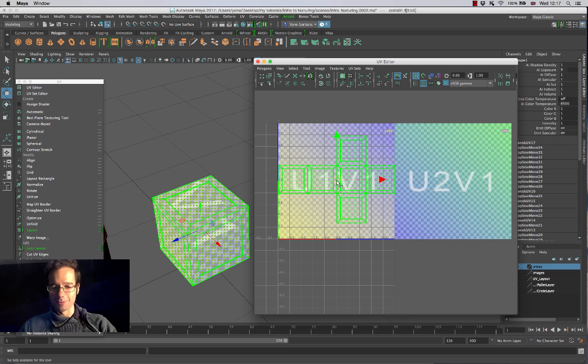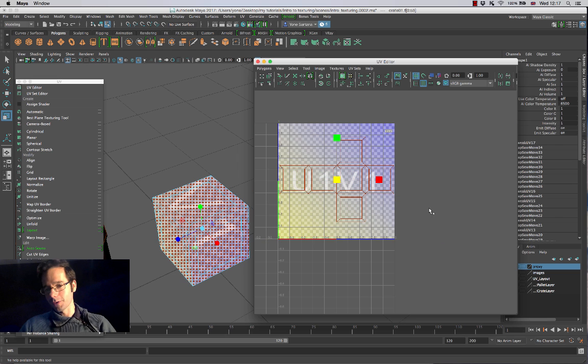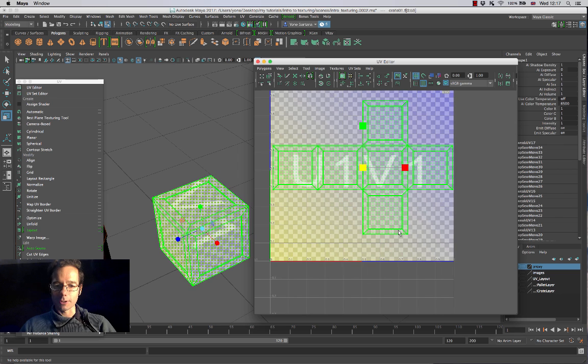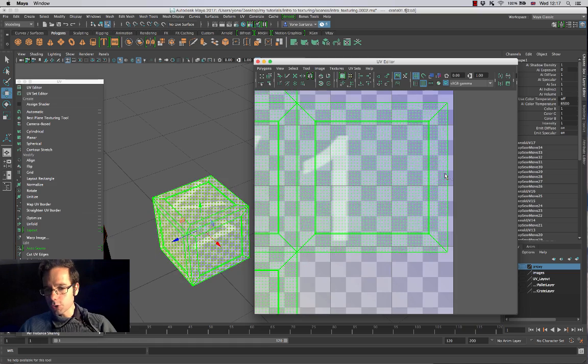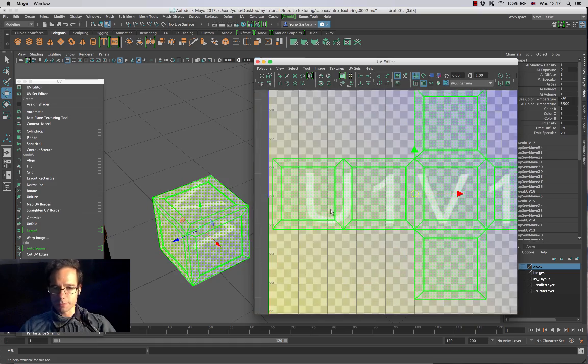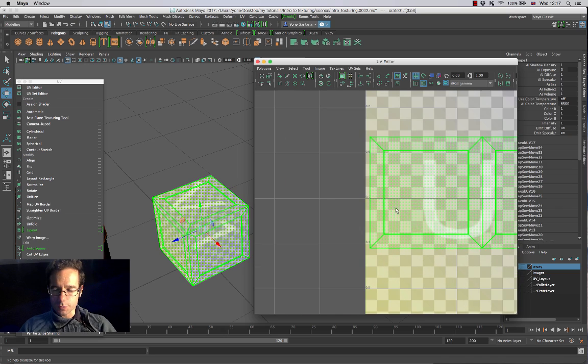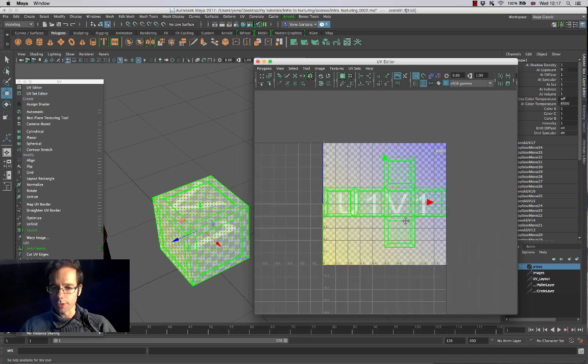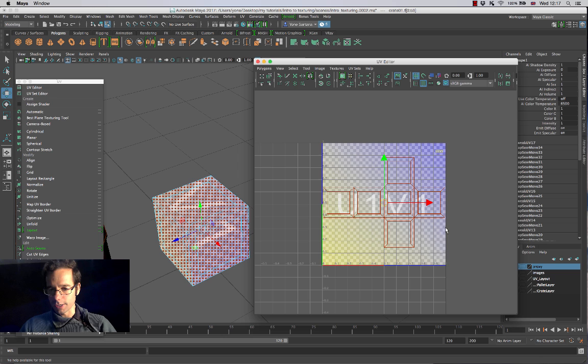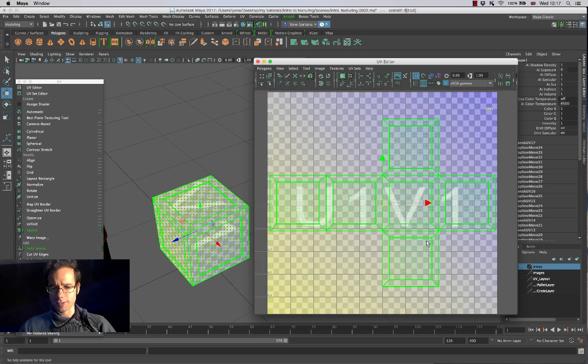It's not the same image as what we were working with before when I was doing my UV unwrapping on my box. So here we go. And one of the things I'm paying attention to as well is making sure that my UVs are actually inside these areas. Sometimes specific game engines or specific productions will require you to not have your UVs right to the edge. Moving things to ZBrush and Mudbox sometimes requires that as well.